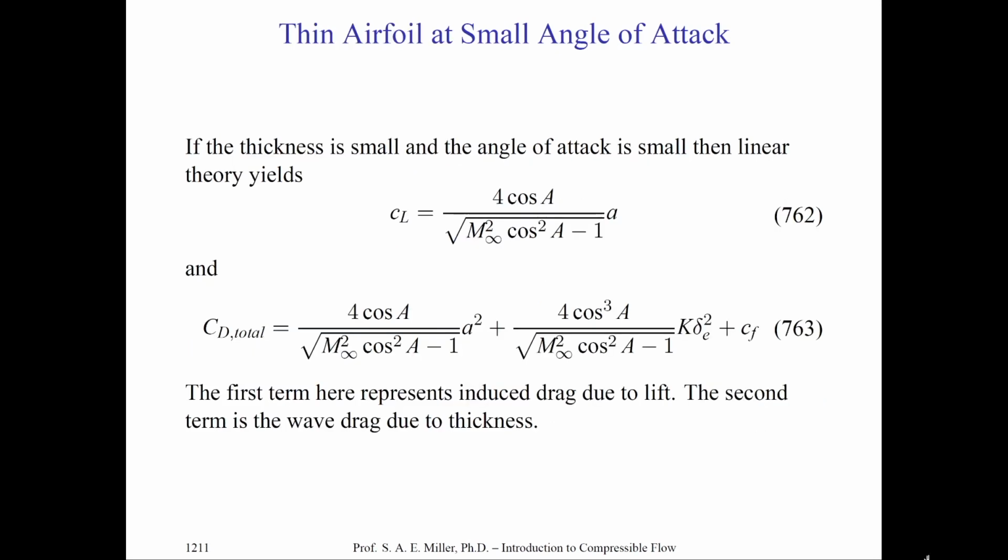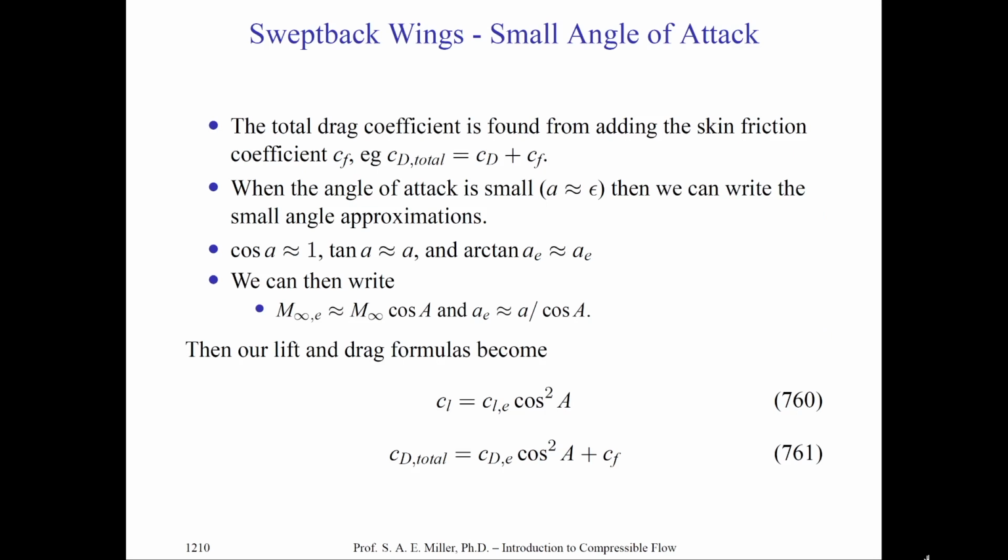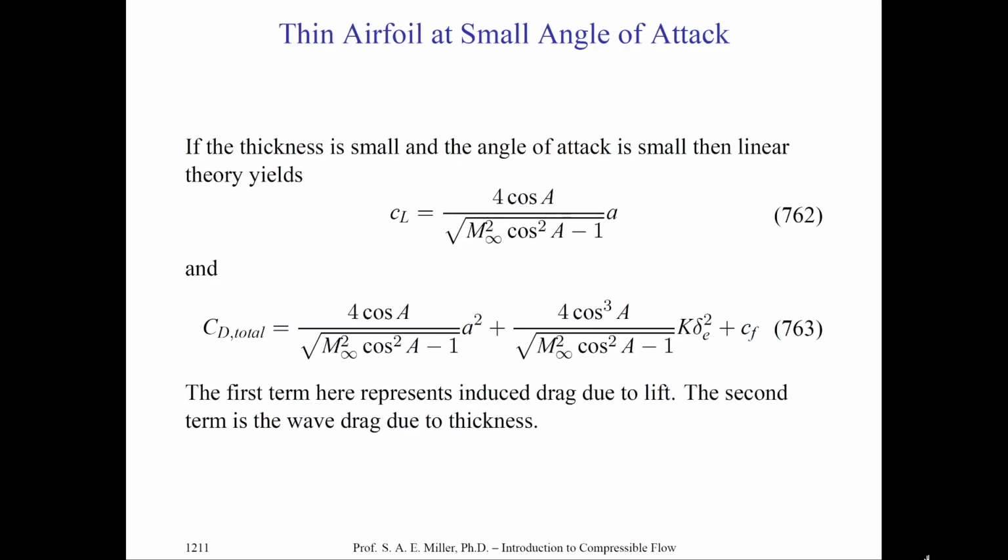We can further say that the thickness is small, which is very reasonable for an airfoil, and the angle of attack is small, and then linear theory will yield the two following equations for CL and CD, which we've used these assumptions and applied previously. Now let's look at these equations carefully.